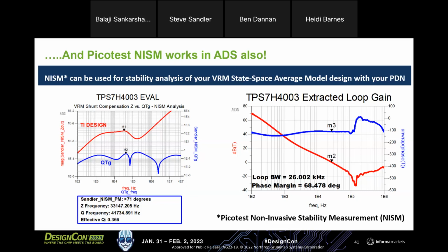One thing that I do talk about a lot in power integrity, and I should mention it here, and I know it was in the slides also, is that right now there's kind of a hard dividing line with power electronics on one side of the line and power integrity on the other. And it's really important that we make that line go away and at least blur it. One of the things that Ben showed today is that his ripple was greatly impacted by the layout of the printed circuit board and the locations of the decoupling capacitors. And so as hard as we work to simulate and model our power supplies off the printed circuit board, it's not going to act like that at all once it gets put into a system.